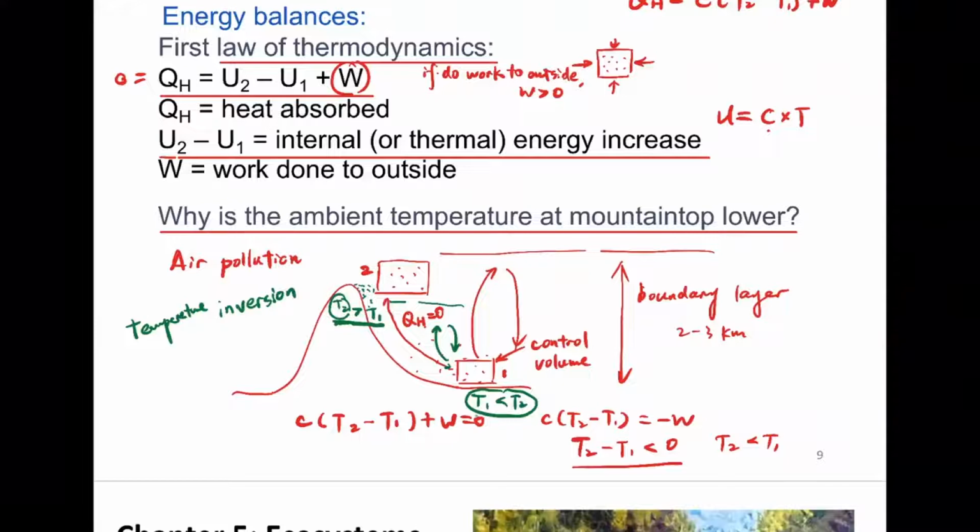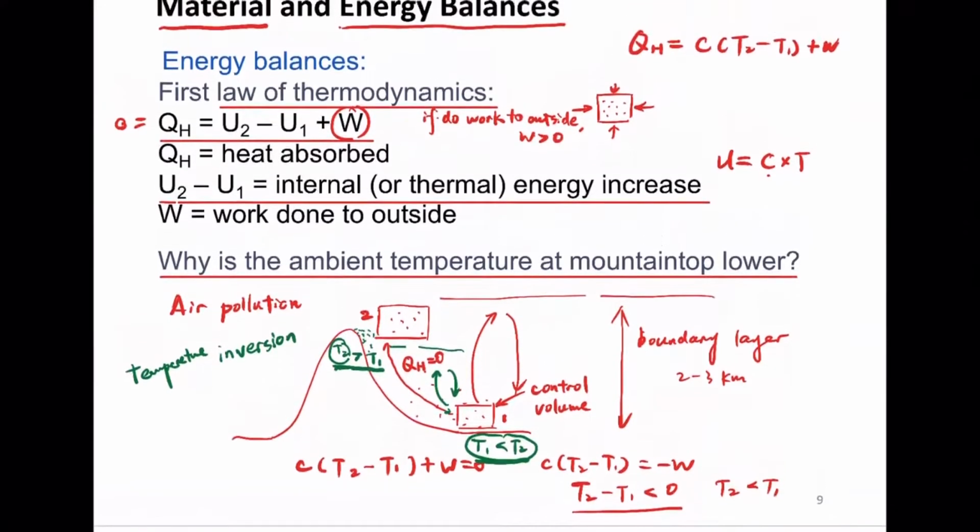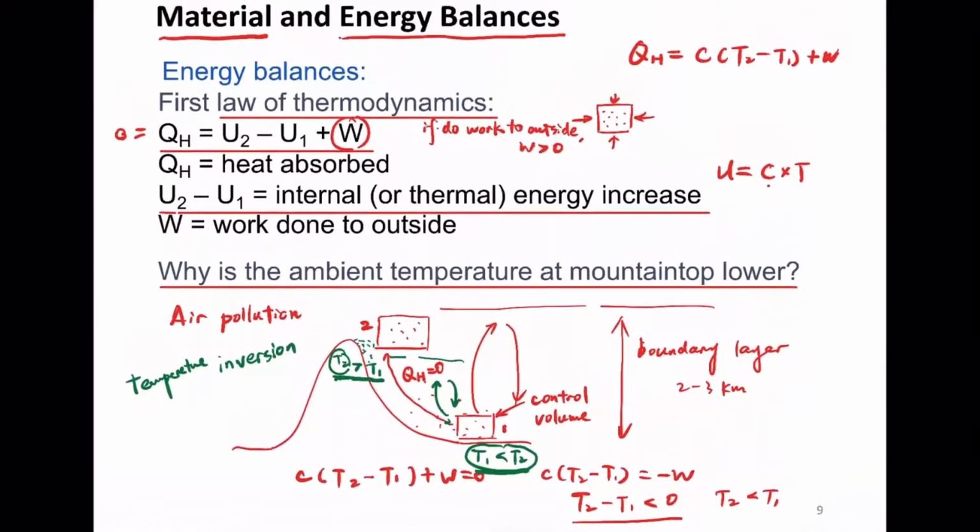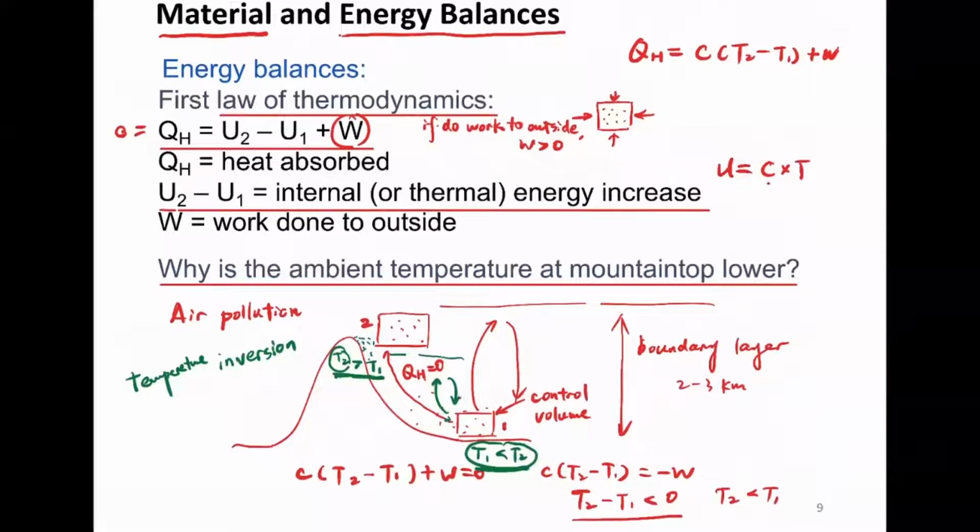So during the night, you're going to have this temperature inversion, which means that the pollutant that's emitted at night cannot move further higher up. They're constrained at the very bottom layer of the air. So it's very inefficient for the dispersion of the air pollutant. We can later find this out at the end of this class, to see how the temperature affects the transport of the air pollutants.